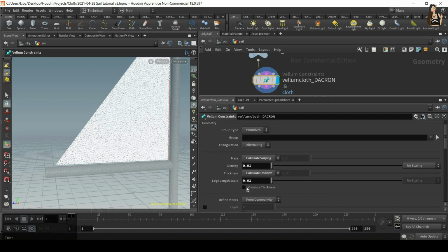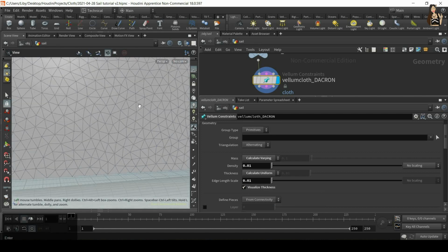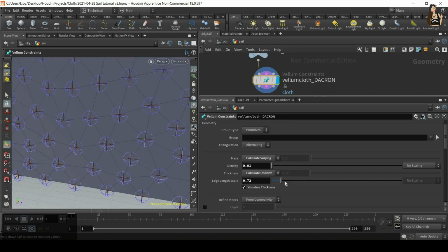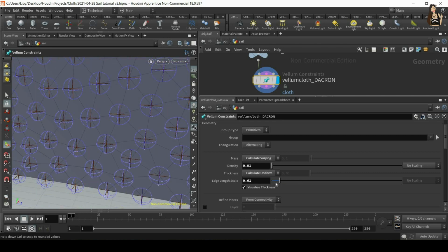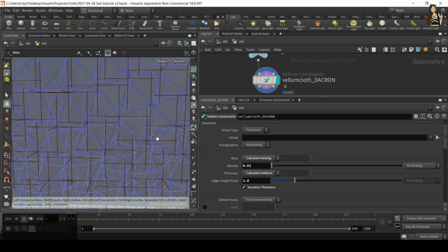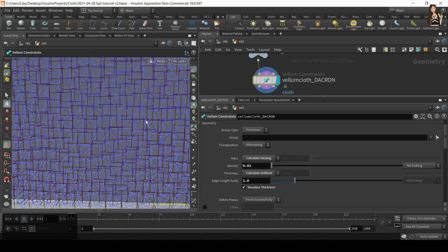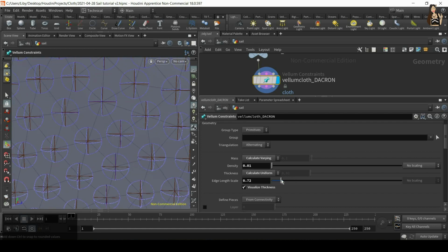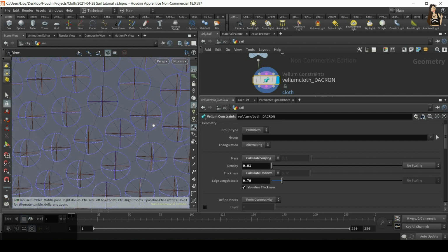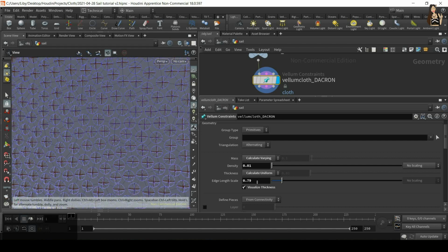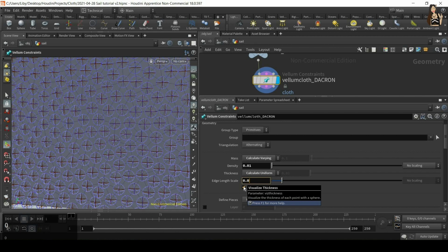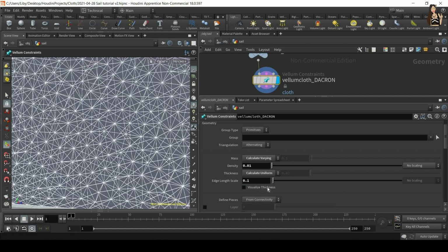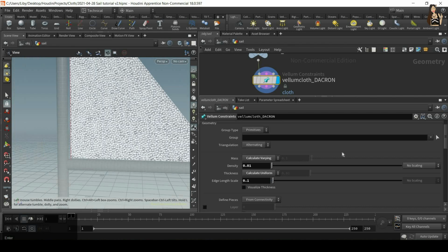to 0.01. You can click on visualize thickness, and here you will see these points. Okay, if I increase the thickness, you will see that these spheres get bigger and bigger. So you can visualize thickness. You should not make the thickness higher than, well, in this case, let's find this value. About that. So you don't want the spheres to intersect, so you need to check that. But I want it to be very thin, so I'll decrease that to 0.1. And now I can switch off visualize thickness. Okay, so these are our two main settings.